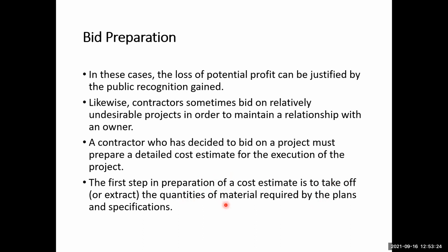If you have the plans and specifications for a building project, for example, then by reading those drawings, we can know how much quantity of the concrete will be needed, how much quantity of the steel will be needed, and related to that, how much amount of labor may be estimated to construct that building, what type of equipment will be needed. So all these are estimated, and this type of estimate depends on the taking of the quantities. Okay, taking of the quantities of the materials by the plans and the specifications.